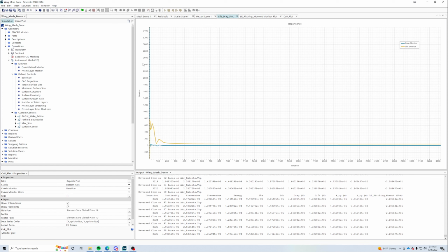If you change the mesh and rerun it, or run it more, and your results don't change, that's good. That tells you you have a mesh that is robust. It tells you you have a mesh that is actually simulating the physics. And importantly, the results do not depend on your mesh very closely. If you change your mesh and your results change a whole lot, how do you know that you're actually simulating reality? You don't, because it depends on the mesh so heavily. But if you change your mesh even significantly and the results don't change, that implies that the physics are actually being simulated accurately.